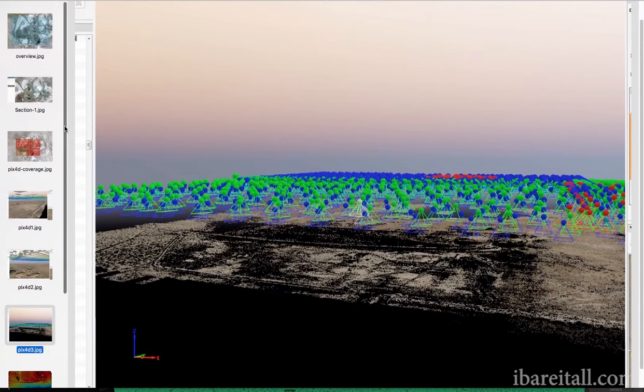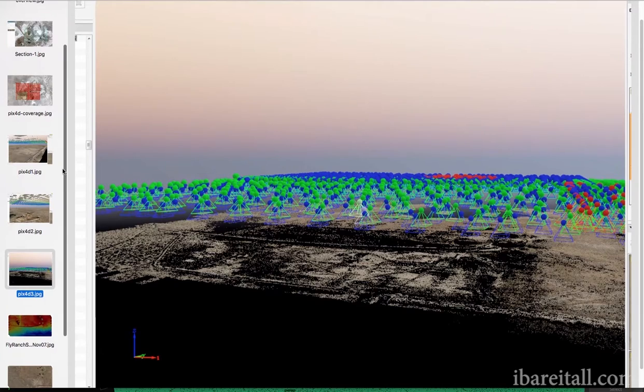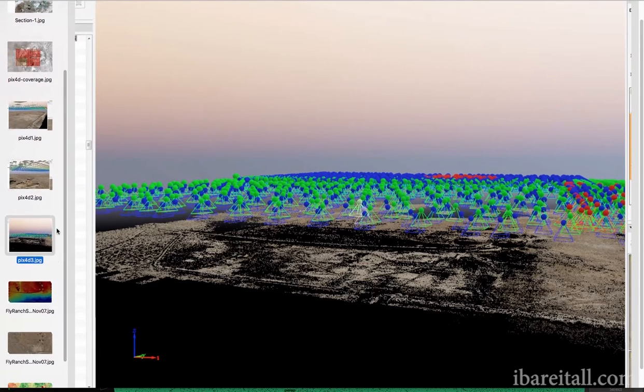One of the things that's kind of unique is when everything's processed, you can create elevation profiles, and that kind of gives you a nice overview of, like, are you in a flooding zone? How high are certain sections? You can also use tools to measure the elevation profile. Draw a little line from one side to the other, and it draws a little graph that shows you how high or how low it is between certain areas.